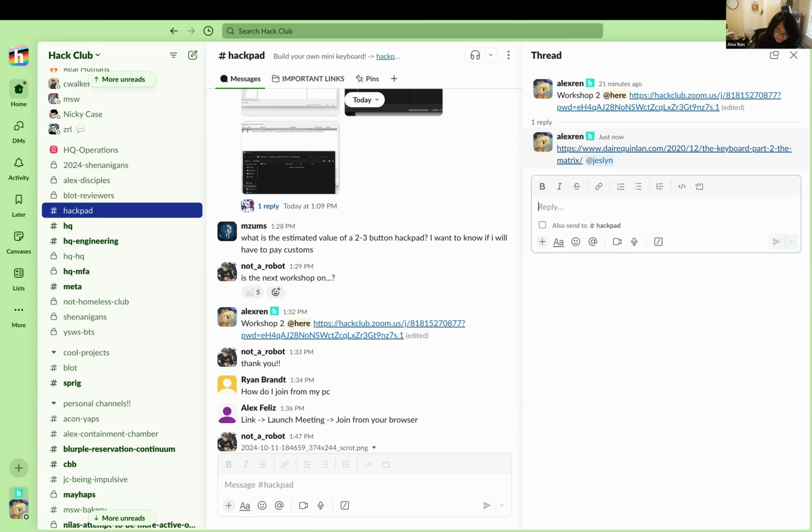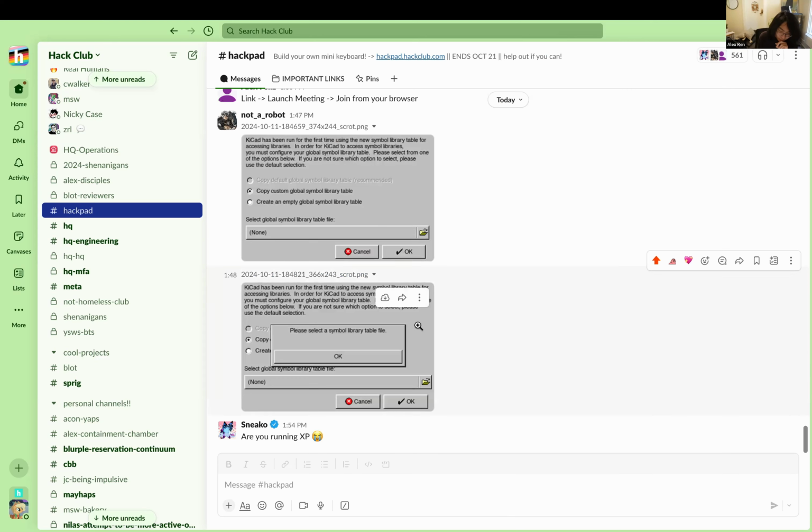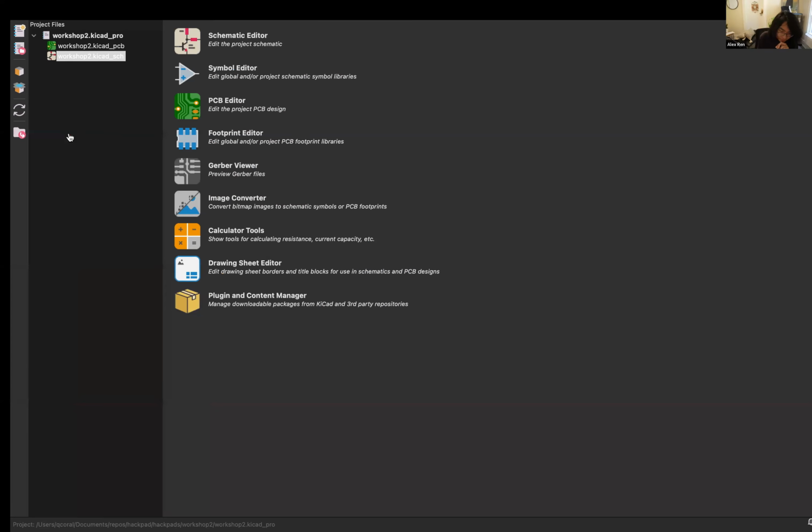Basically you can create a multiplication table of switches. If I wanted 20 switches, I could do 5 columns and 4 rows, so I would only use 9 pins instead of 20 pins. But we'll start small for now because it's easier.